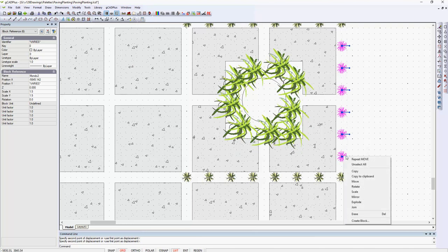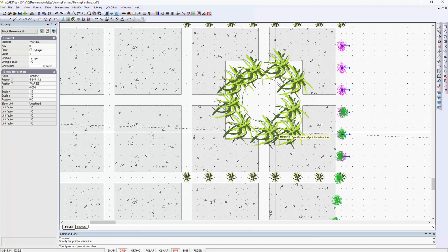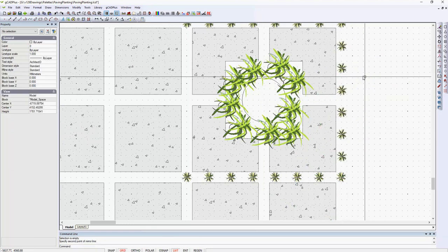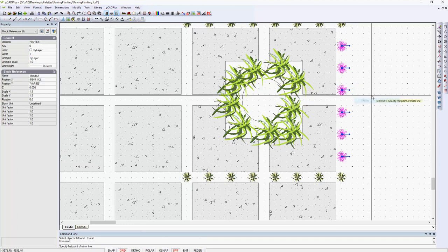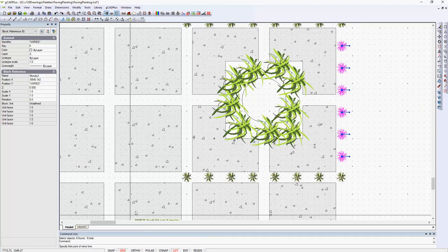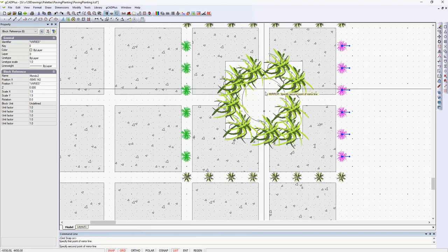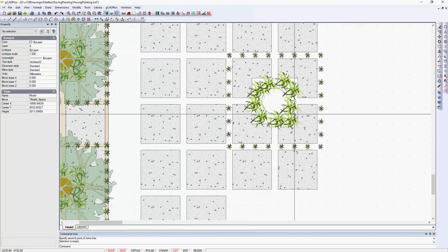And now we've got them selected, we can mirror them across this center line. Whoops, try that again. We just want this central group here, mirror, and we now need to put snap on so that we can click there and like that. So there's our design taking shape.